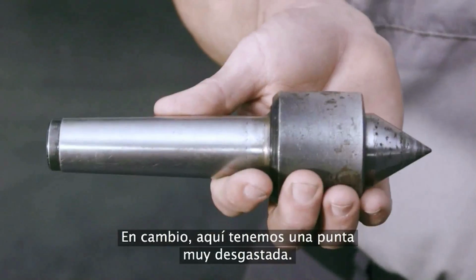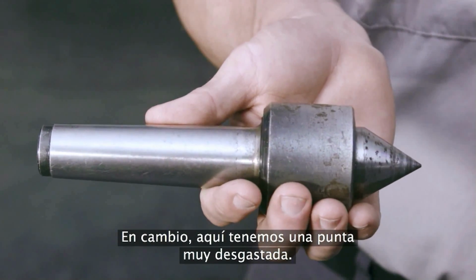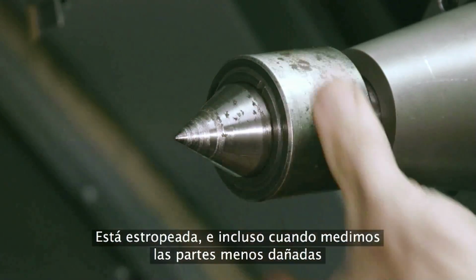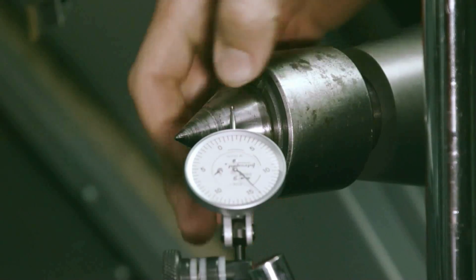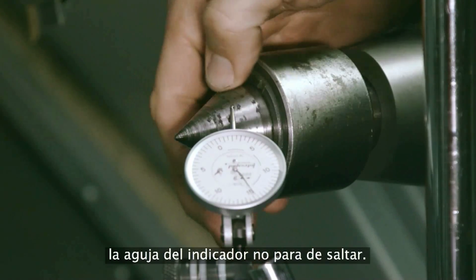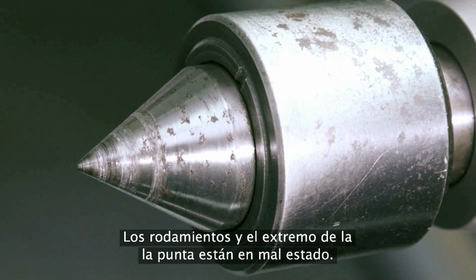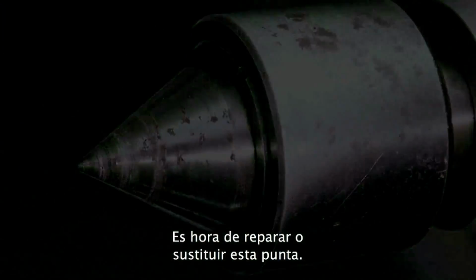In contrast, here we have a well-worn center. The tip has significant damage, and when we indicate even the smoother sections, we get jumpy indicator movements. These bearings and the center's tip are damaged. It's time to rebuild or replace this center.